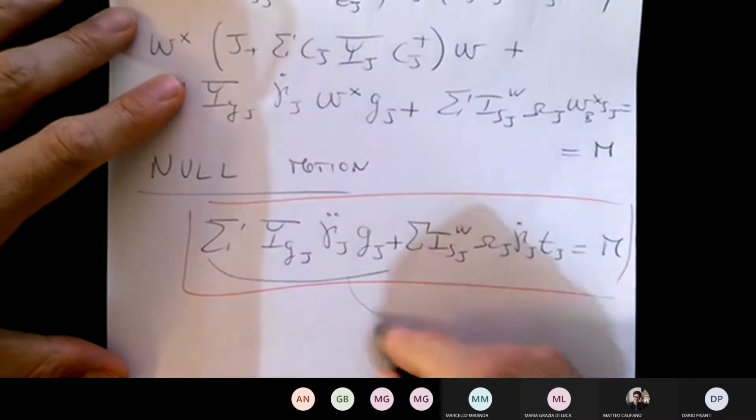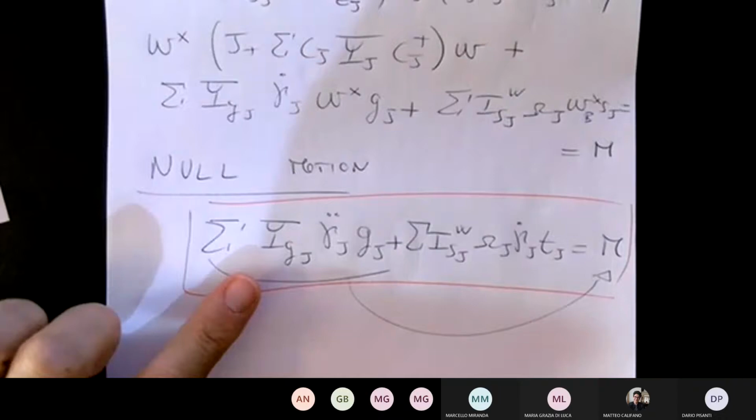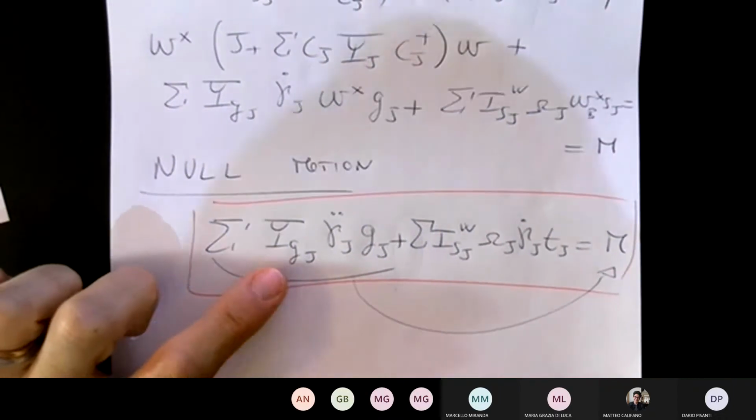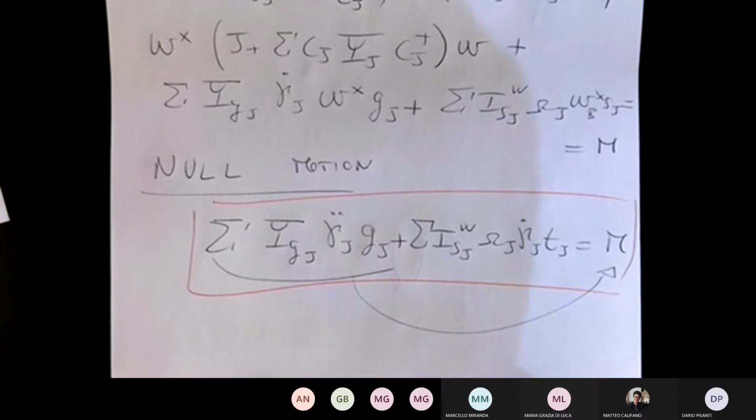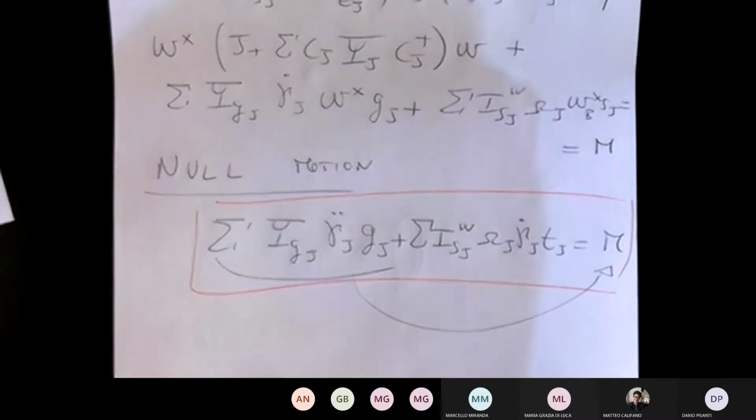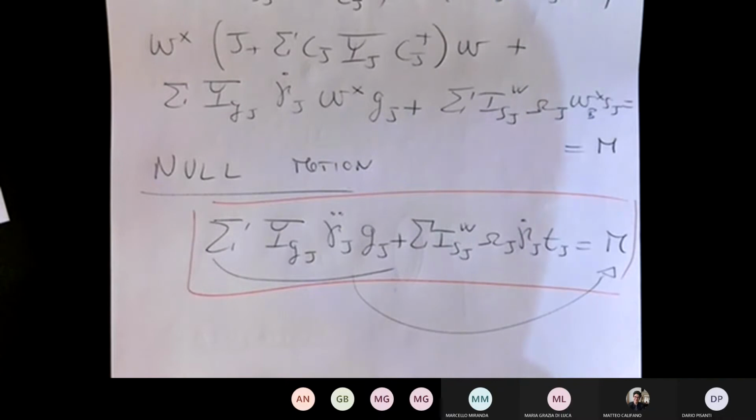So this is really not actually used in the control design approach. This usually goes into the disturbances because the moment of inertia about the gimbal axis is quite small by construction compared to the moment of inertia about the spin axis. So it's really not that useful, and it's considered a disturbance. And plus, you will have to control the acceleration. That's not usually done in practice. You don't control accelerations with actuators, really.